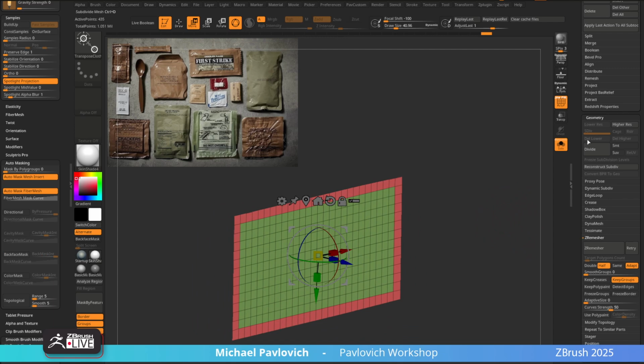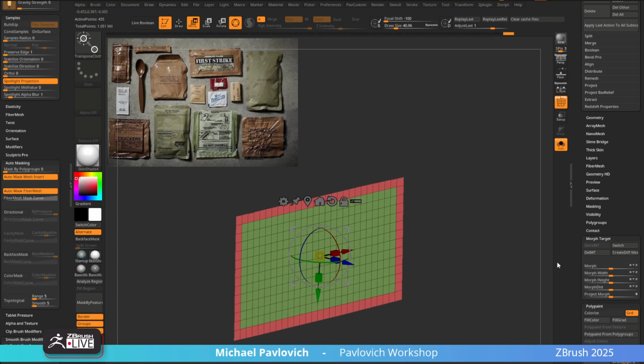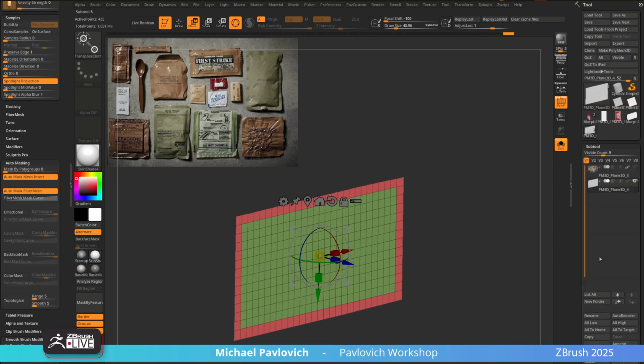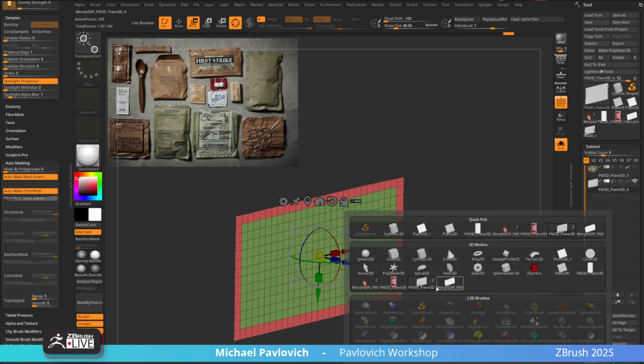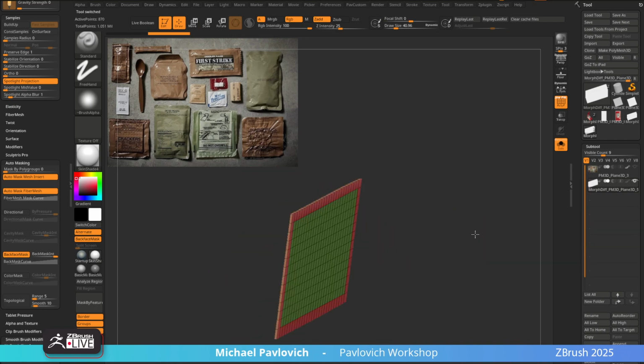I'm just going to go through here with a morph target, store it, drag this out a little bit here, create diff mesh. And now I want to keep working in this file. So in that morph diff that it spit out, I'm just going to say append that latest Morph Diff. This Polypaint I don't really need anymore, so we can delete it. Keep a nice clean file. So now we got both here.